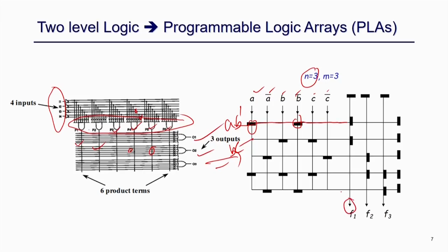So now it may not take all the products. So there are say 6 products here, 1 2 3 4 5 product terms are here, and this is taking only these 2 product terms, right. So this F1 effectively means A B bar plus B C, right. So F2 is basically taking this product term and this product term and so on, right. So this way I can represent my overall circuit in these two representations.